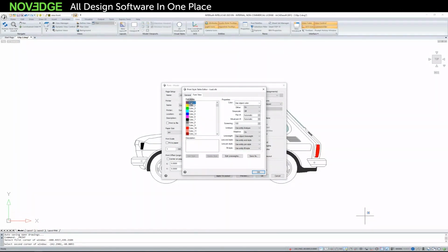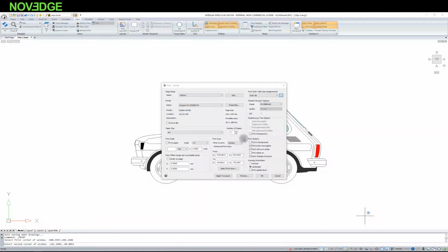And then you enter such a template, and in the properties, you define what thickness is assigned to a given color. Having such a template, you do not define these thicknesses in subsequent drawings, because you have your style defined by yourself. You just use only the same colors and print the project in the same way. Some companies work so that everyone has the same print style, everyone draws exactly the same way. Thanks to this, the way the drawing is printed is the same.